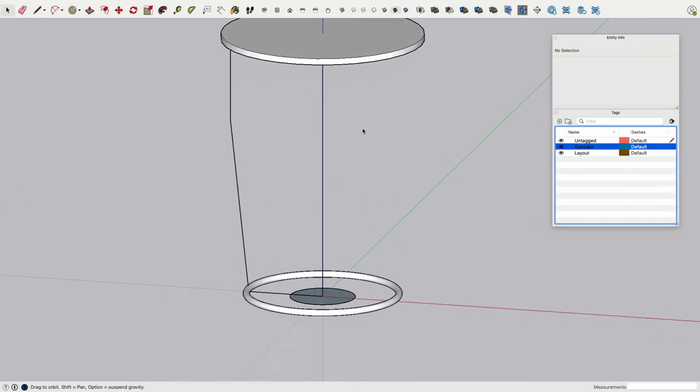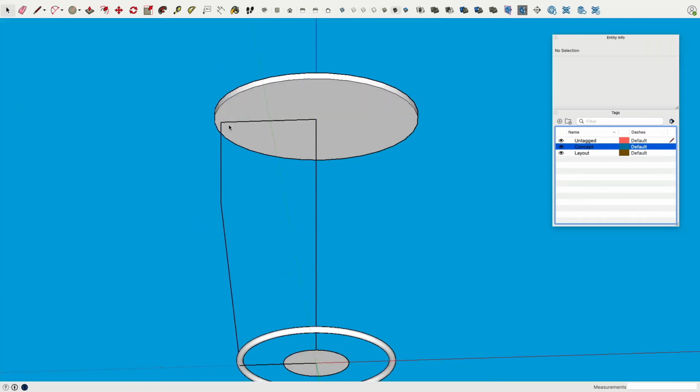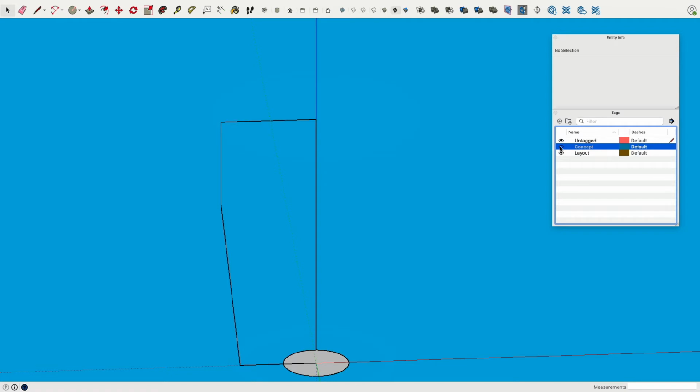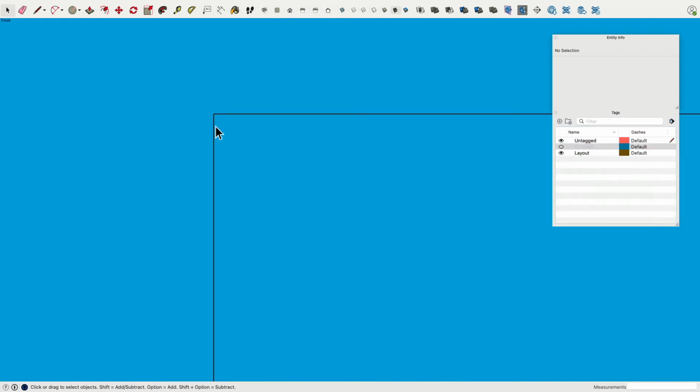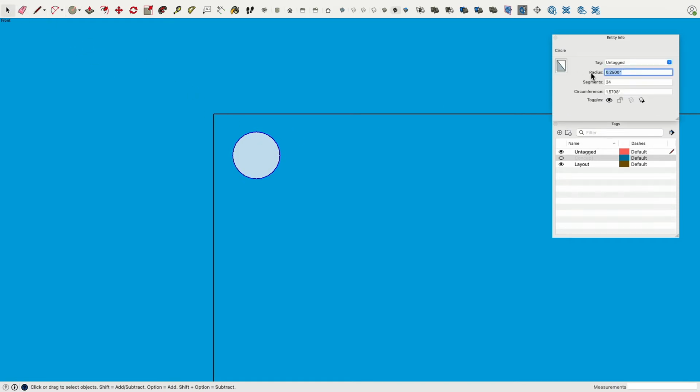Very good. Okay. Let's make another one there. I will hide this for the moment, so it's easy. Then again, working clean now is very easy when we go to a side view, because then I can zoom in here and create my, you see how again, this line is red. So I have endpoints horizontally, vertically. Then this should be 0.25 and we set 32.